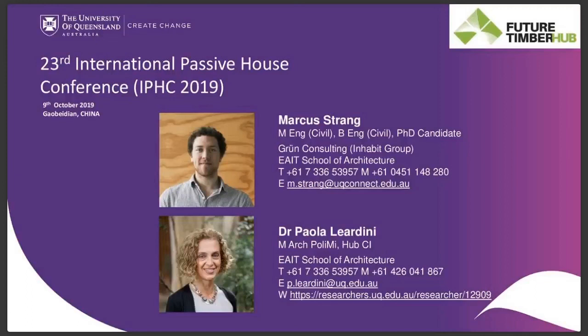And with softwoods, the durability is not as good as hardwoods, and there are some CLT manufacturers that are starting to look into hardwoods being used, like eucalypt, and they do manage moisture a bit better. However, it's also worth considering treatment as well. So in Cairns, it may need to treat the timber using something like a CCA treatment, depending on how you feel about treatments being used. That might be a solution.